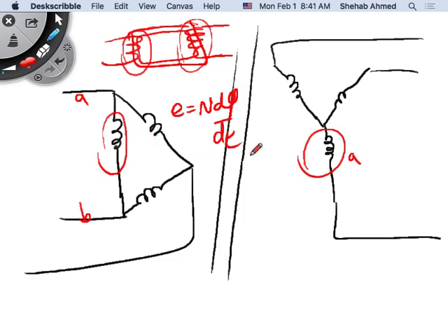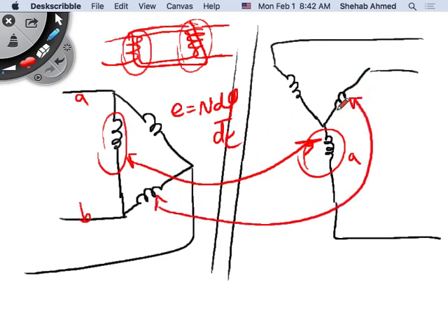Okay, so let's continue. We will go through that in a lot of detail. But let's continue for a little bit here. This will be in phase with this. The magnitude will be depending on the number of turns here. But assuming they're 1-to-1, I will answer your question, right? And then this one and this one, we will assume in phase. This one and this one, we drew them in parallel, so these will be in phase. And this one and this one, we drew them in parallel, so they will be on the same core. Right? Now I can take my 3 windings on the secondary and connect them in star, or I take 3 windings in the secondary and connect them in delta, right?